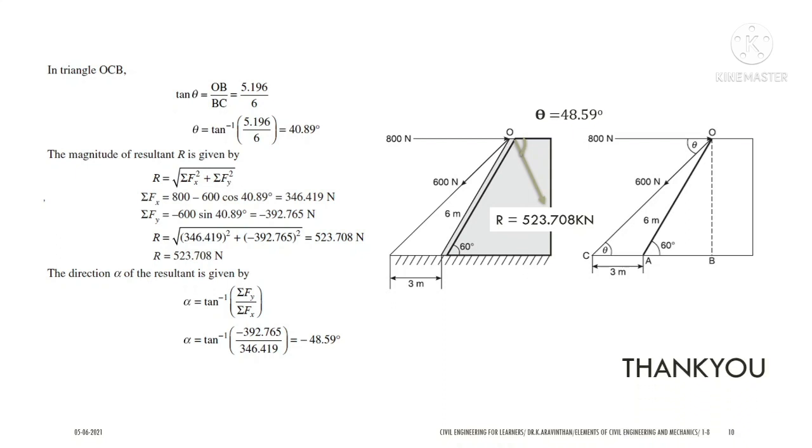So by this, whatever might be your example and case of your problem, first make it into axes, and you can take x axis and y axis, and after that make all the forces' angles with respect to horizontal, and after that you find the summation of Fx and the summation of Fy. You can find the resultant and the theta for the resultant, and if any unknown forces are given, you can find them by using this concept. I hope you understand certain concepts here and you got some confidence.